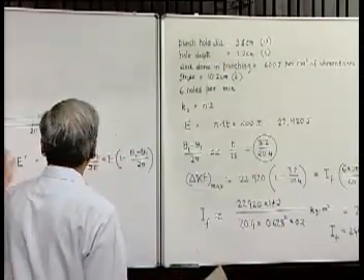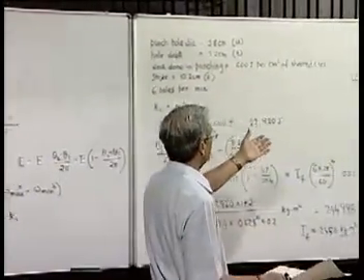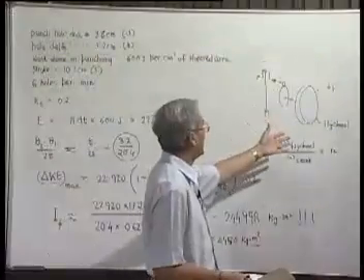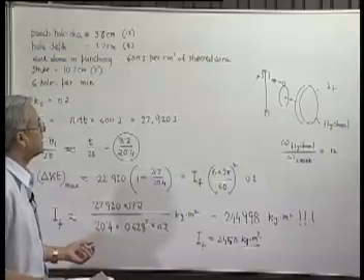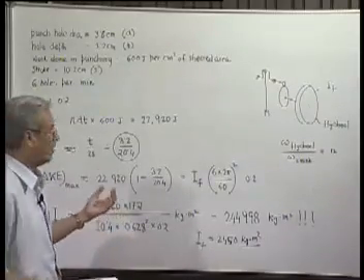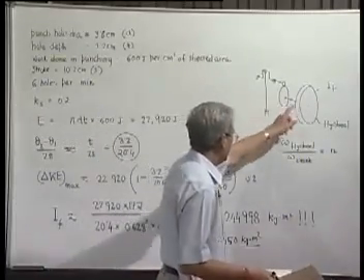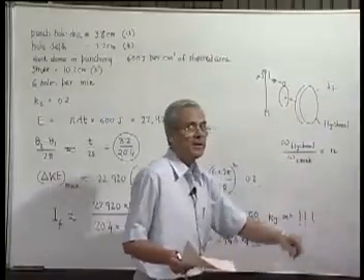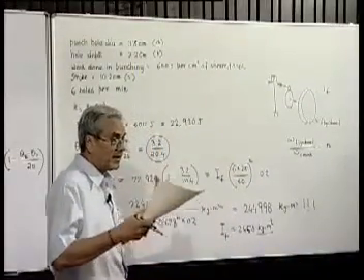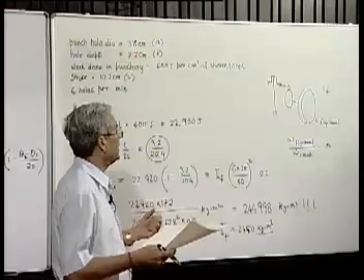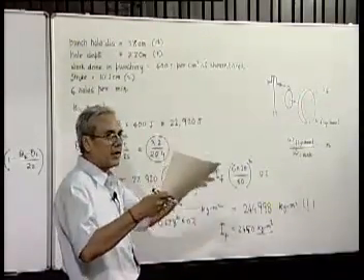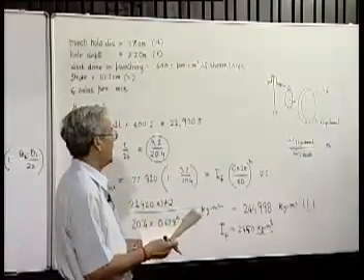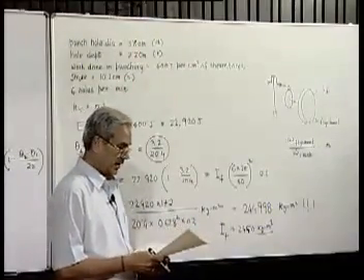What we can do, we can use an idling shaft on which the flywheel is mounted and which is connected to the main shaft or crankshaft through a gearing system or a transmission system. What we are effectively doing is making this real source of kinetic energy rotate at a higher speed. That will make the requirement of the inertia lower and the machine will be much lighter.